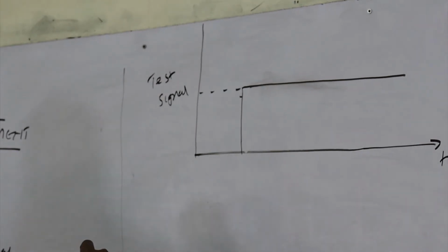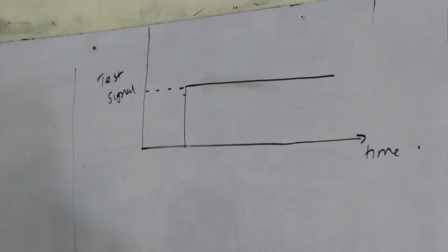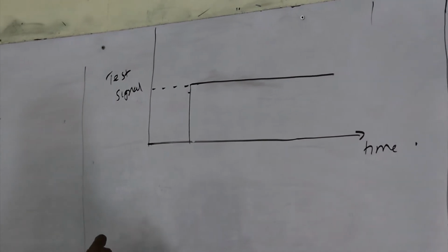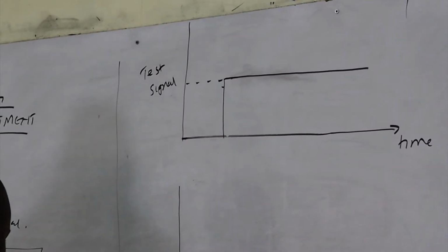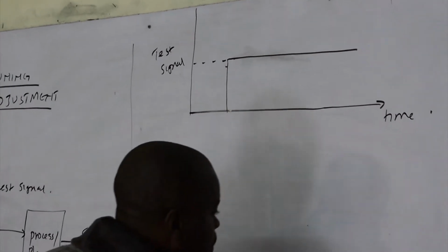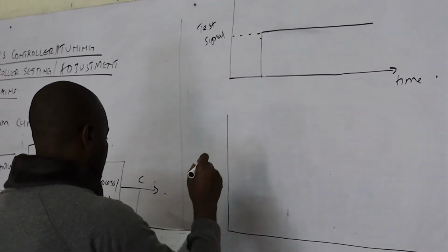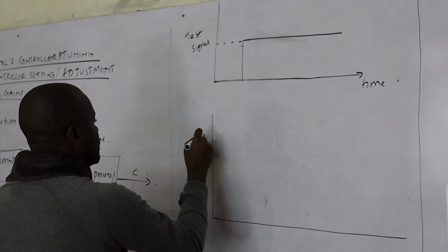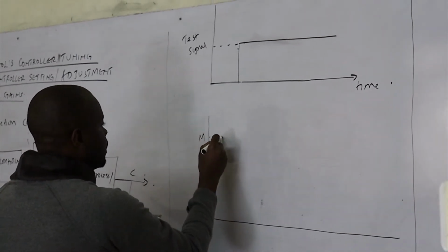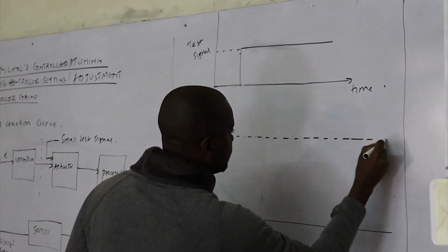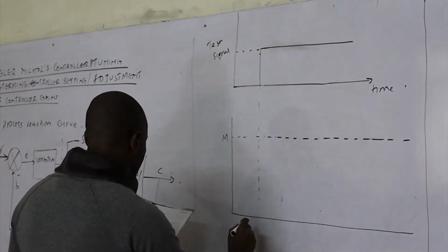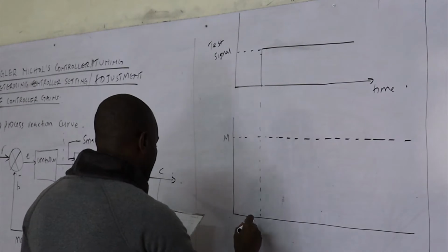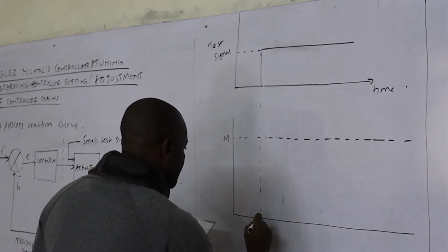You can have some given value P. This is the test signal that was injected in the actuator. Then we can have the corresponding measured signal, also in percentage. We have measured signal M going in that manner, and at this point we can have a sigmoid, almost S-shape.